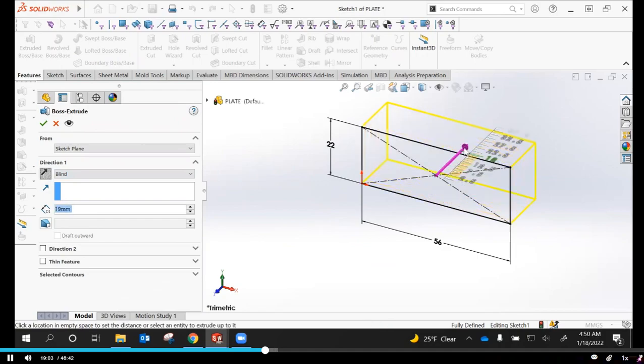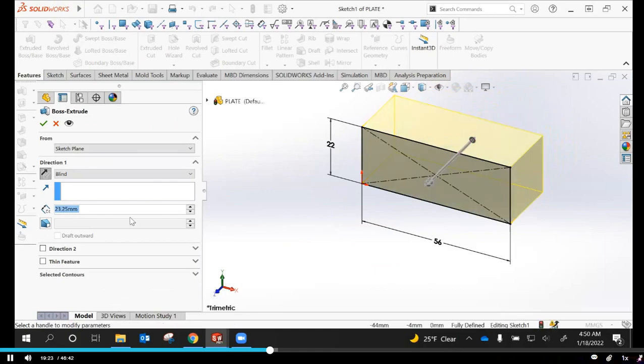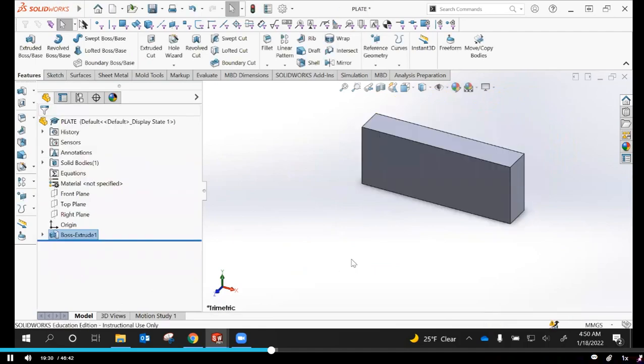You can also drag like this if you like, and it will tell you along this scale, it'll stop and click at various points. The size of those stops can be determined in your properties. But again, we will just type in 10 because we know that's what we want. Click enter and the green check mark. Now we have our 10 millimeter part.